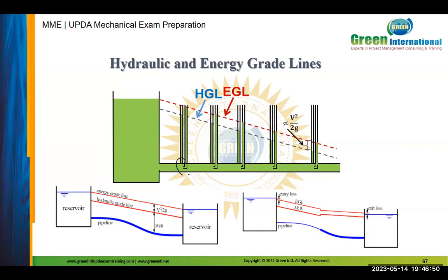What is measured here? Velocity. One is for the stagnation condition. What happens in the stagnation condition? It measures the total head, which refers to total energy. And the other one, just a little, measures static only. So one measures total, one measures static.